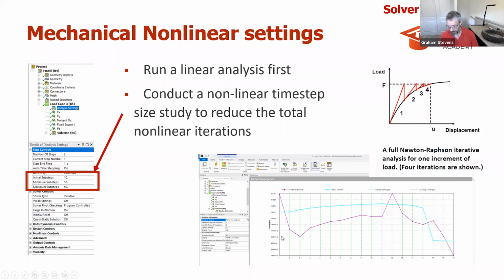So for this analysis here, you can sort of see from 4 to 10, there wasn't a whole lot of change here. So we probably don't need 10 steps initially to run here. We could probably get away with 5. Well, you may want to test that. And so you would run it with 5 only to ensure that you're still getting convergence. And so optimizing these number of steps can definitely speed things up. And so you can also start small and run it at low time and make sure you're getting convergence and look at convergence, and then expand to see if you need to.